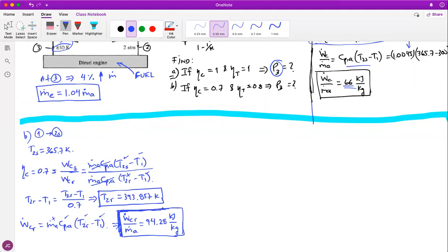Okay, well, and so what? Well, nothing. Now let's just go for the 3 to 4s. But you have already done it. Yeah, I know. So P3 to the (1 minus k over k) times T3 to the k over (k minus 1) equals P4. You already did this, I know. Be patient. T4s. And this is not actually your problem because you already did something about it. Why are you doing this again? Well, I'm just doing it again because I need some structure.